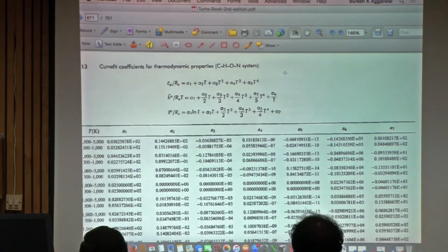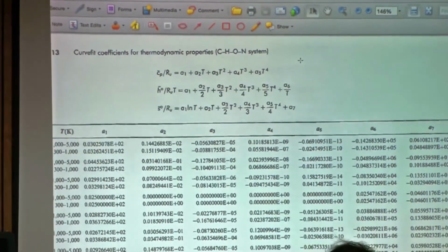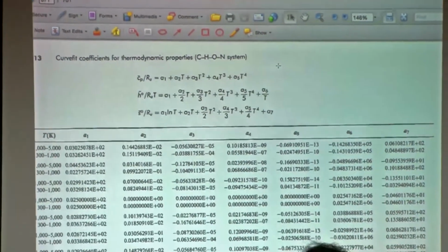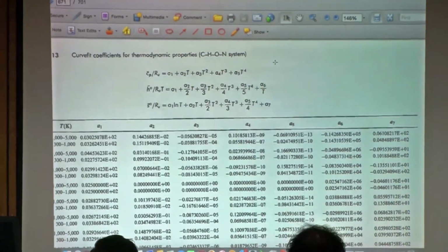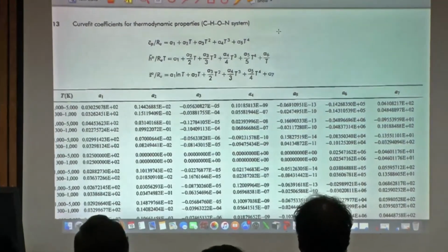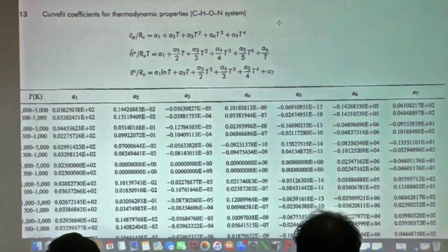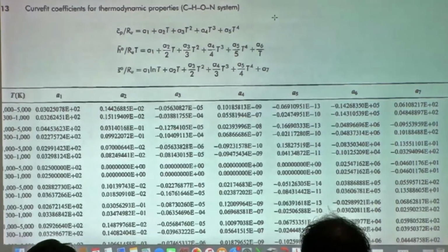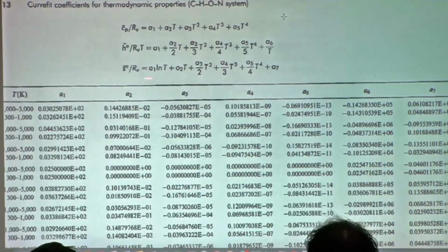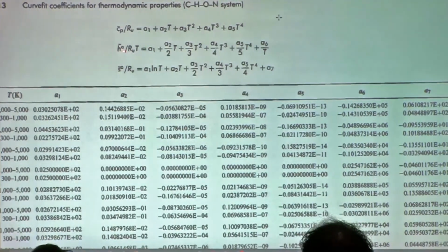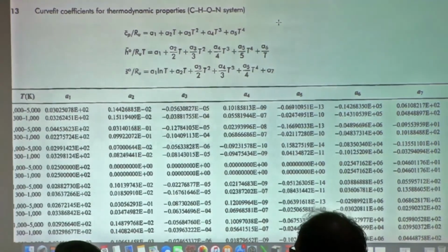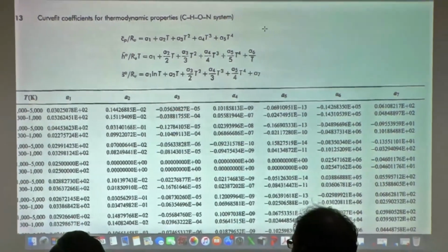This is the common way to write Cp as a function of temperature for different gases. Okay. So you see this is a 4th-degree polynomial, and these polynomials are curve fit to the experimental data. Then you can also write the enthalpy as a function of temperature, because remember, enthalpy is the integral of Cp dT.